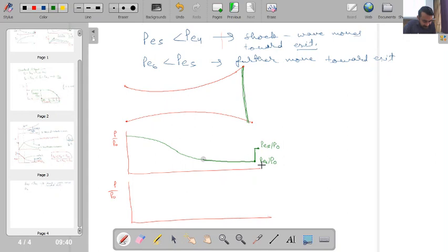So now say, let's assume that this PE6 whatever we are having, that is nearly equal to PE0. That is something which is happening over here. So PE6 is almost nearly equal to PE0, which is the pressure required to maintain complete supersonic, isentropic supersonic situation at the exit. Okay, then I will be finding that I have a shock wave exactly near the interface.